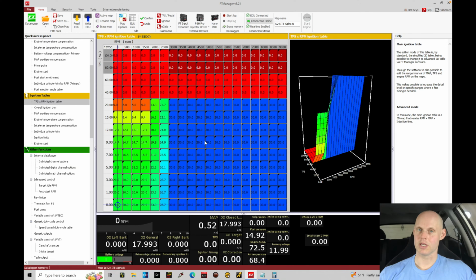That's why I put 30 degrees. It gives us good spark timing to have some decent torque output out of the engine. We're probably not going to be reaching maximum brake torque with 30 degrees, but we'll be close, but it'll be reasonable so I can drive my engine.